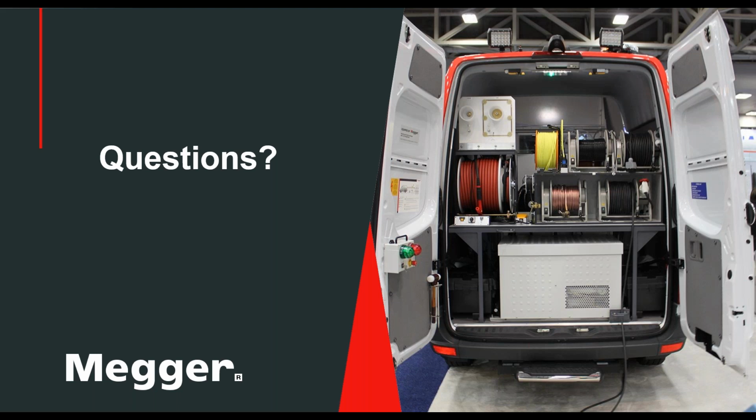And then I guess the question was specifically about PILC cable. In general, you do use larger, heavier duty thumpers with larger capacitors, because, as Henning mentioned earlier, with the laminated insulated cable, the oil itself does not flash over nearly as easily as an air gap.